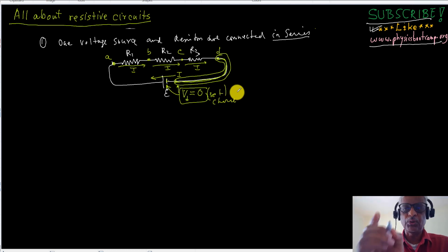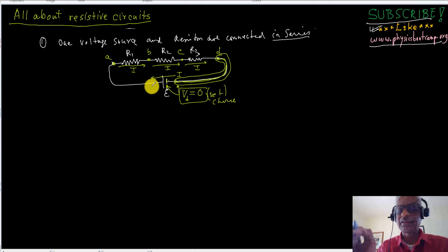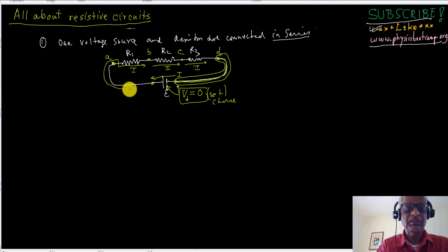I can make one choice for the potential. That's like a reference electric potential. And this side, all of this is going to have the same potential, because there's no resistance here. We assume this resistance is included over there. So this is somewhat mathematical, right? It looks physical, but we're assuming these wires don't have any resistances because they're all included in here. Okay, so all of this will have the same potential. So potential at A will be E. So this is 12 volt.